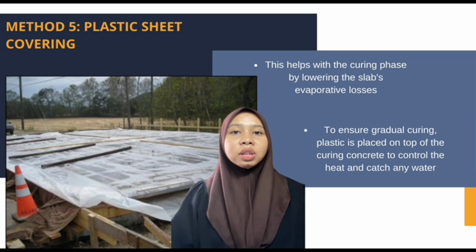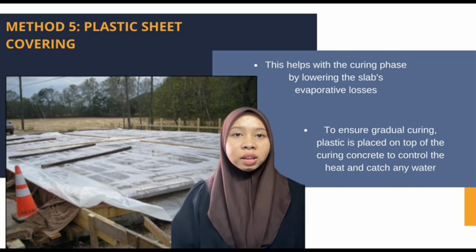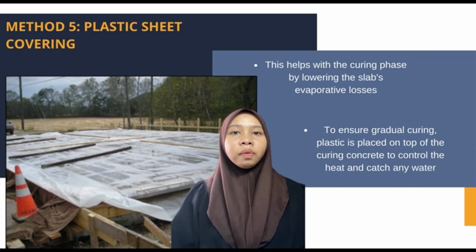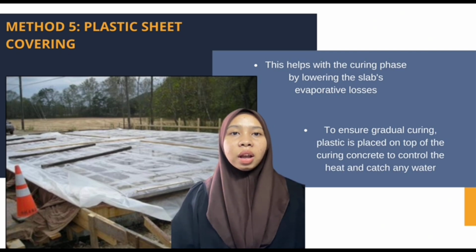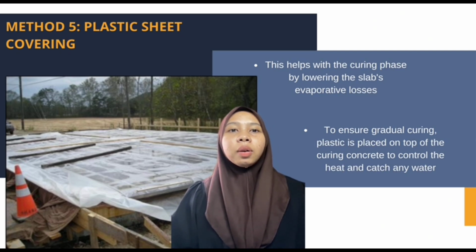First, use dark plastic if the temperature is below 60 degrees. Second, cover the concrete with a reflective white or metallic covering if the temperature climbs above 85 degrees. It is apparent that using plastic covering can help the concrete cure without cracking.